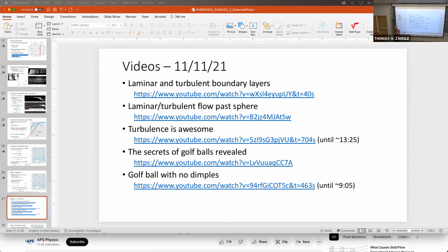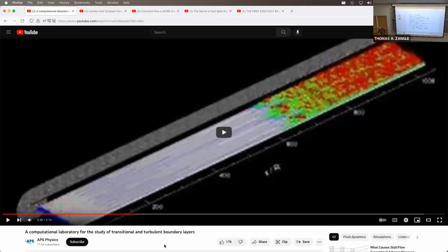You'll be using the RANS equations and some kind of turbulence model to approximate the impact of turbulence on the mean flow. But we don't have to do that. In theory, we know that the Navier-Stokes equations still hold in turbulent flows, and so we can also just ignore all that RANS stuff that we talked about last chapter, and just straight up simulate the full Navier-Stokes equations, and that's called direct numerical simulation.